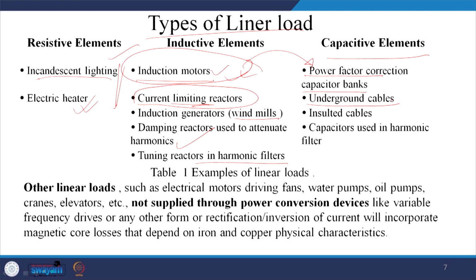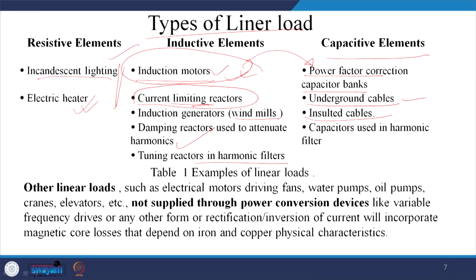Then there is the underground cable, because these may be at a different potential, and due to that, the soil between them acts as a dielectric. So, ultimately shielded cable also comes into the picture. This cable itself also behaves like a capacitive element. Insulated cable in the same way behaves like a capacitor element, and there are capacitors used in harmonic filters. That is intentional use, but the cables come into the picture because of their inherent property.